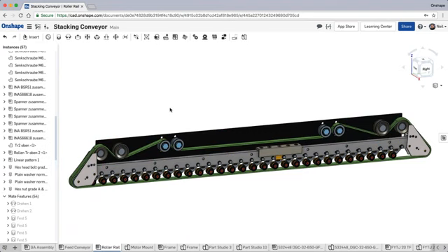One of the things that makes machine design, there's a question there saying, can I make configurations in parts? Yes, you can. I'll come on to that shortly. One of the things which is very prevalent in machine design is standard parts, standard things like belts, chains, sprockets, gears. Again, all this stuff can be generated automatically, and we use this thing called feature script.